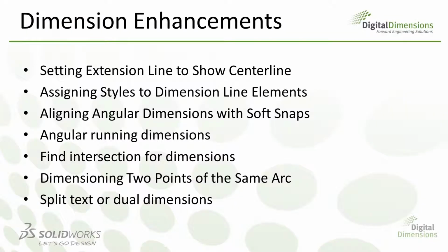And for SolidWorks 2014 What's New, the dimensions got a lot of attention here. So we now have complete control over the extension lines within our dimensions. So we can do things like right-click on a dimension line and set that dimension extension line to be a centerline font. This will be helpful for dimensioning to holes, and this will show the reader of the blueprint that you are again dimensioning to a center line.